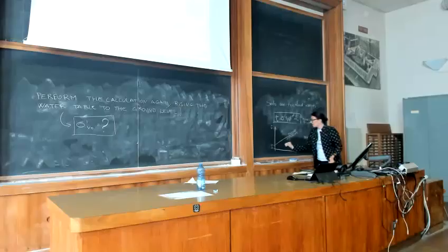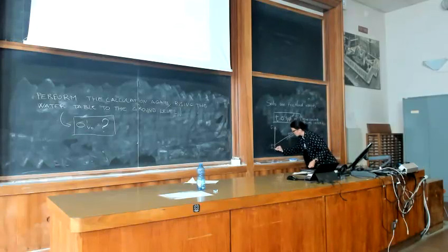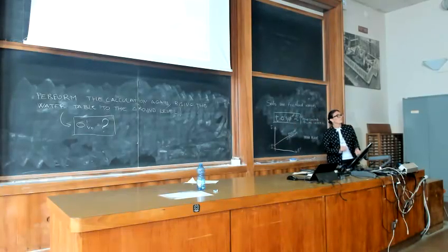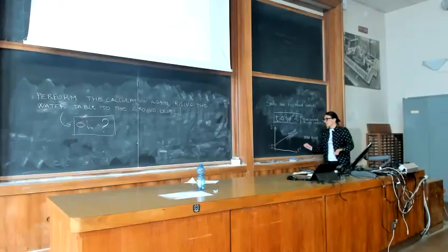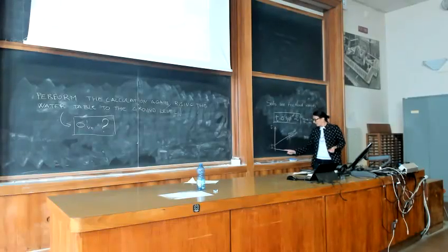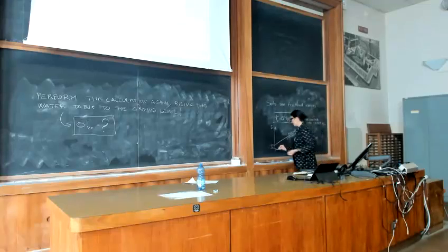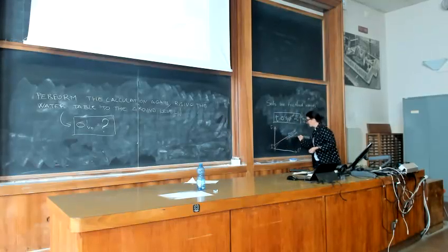Okay. The real failure envelope is a curve which starts from 0 for most of the soils that we can find in nature. It starts from 0 because at 0 effective stress, the soil does not provide shear strength. Then the shear strength increases and it is a curve like that. So it is a curve, not linear.